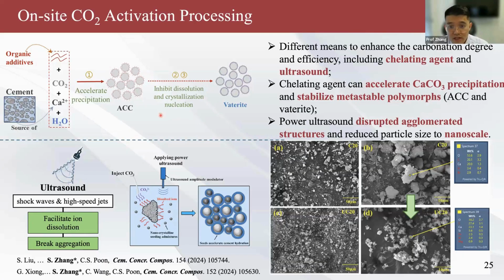Also, we use ultrasound to control the particle size of the seeding material, because the shock waves and high-speed jets of ultrasound can not only facilitate ion dissolution but, by limiting aggregation, control the particle size of the seeding material down to the nanoscale. And once you have a smaller particle size, the surface area is higher, and the reactivity of this material is also enhanced.